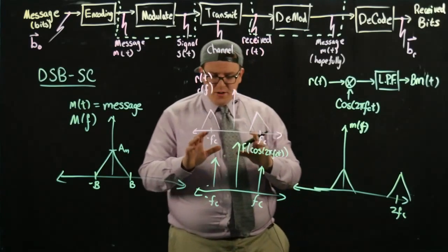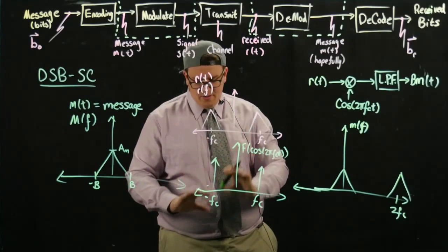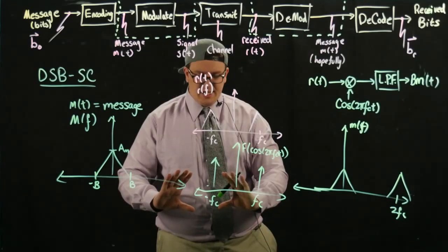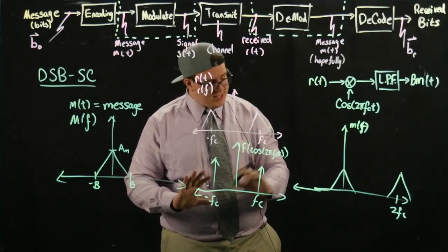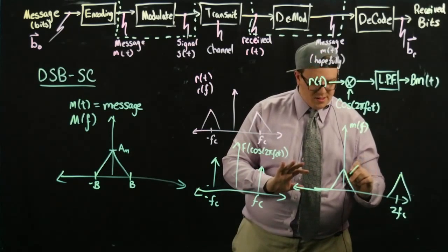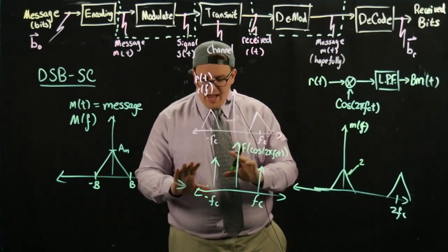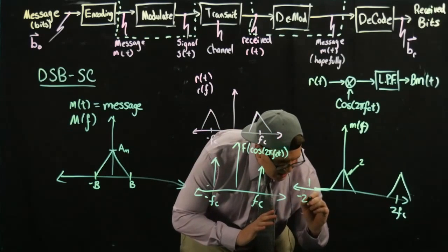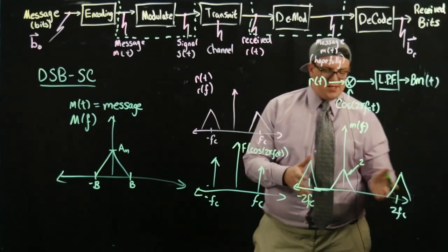And if we do the other delta function, we center 0 at minus fc, which means if we take this whole thing and place it here, a plus fc is going to center it at 0 again. So this actually just gets added on top again. So there's 2 of these. And we also get one at minus 2fc, which isn't surprising because we want this to be symmetric.